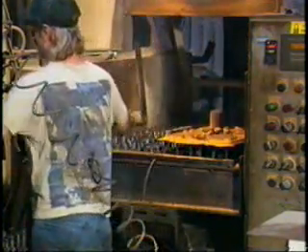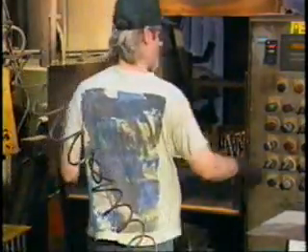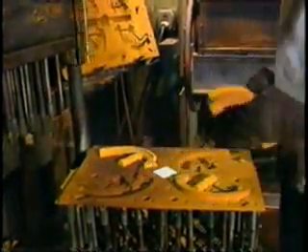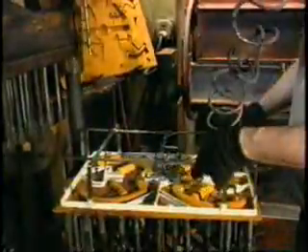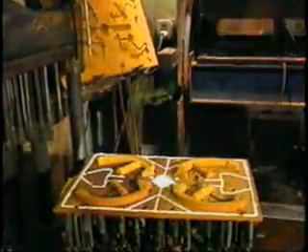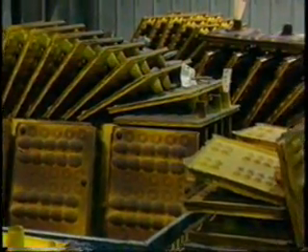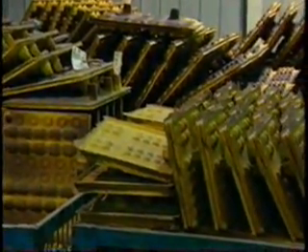Once cured, the hardened shells are removed from the pattern and serve as mold halves. Shell cores, which are produced similarly, are placed within the drag side of the mold. A bonding adhesive is then applied, and the cope side of the mold is aligned and secured, creating the finished shell mold. These shell molds can be produced quickly and store well for extended periods of time.